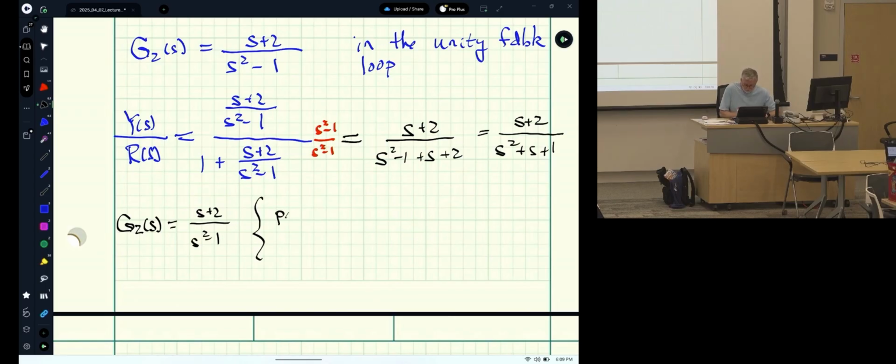Let's just do the poles and the BIBO first. We'll come back to zeros again, but we don't need it for the stability, and we know that, so let's just stop computing it. So it's S squared equals 1, and so the poles are plus minus 1. BIBO, no. Darn it.